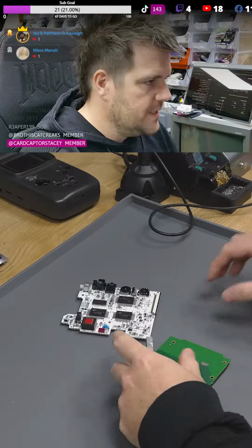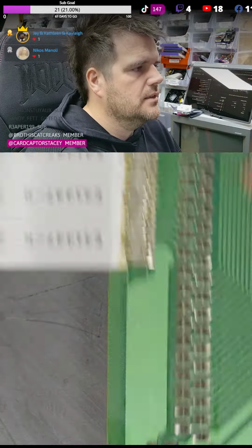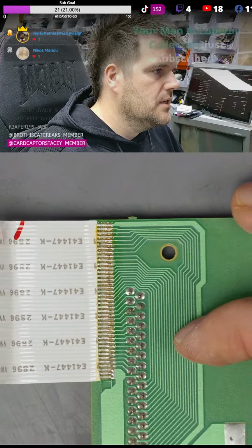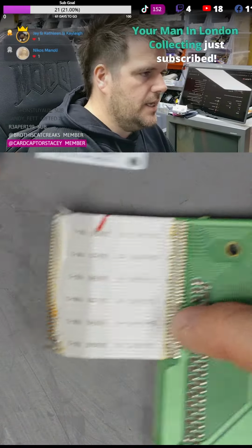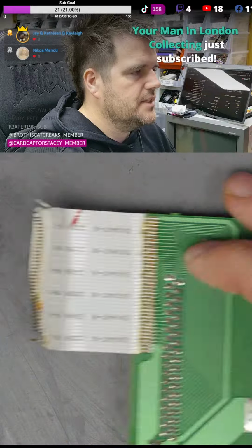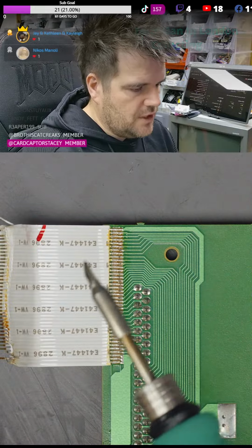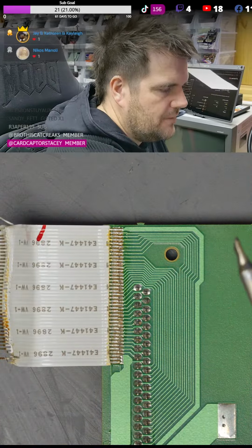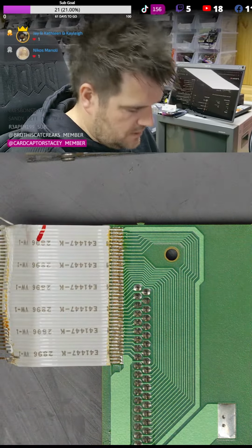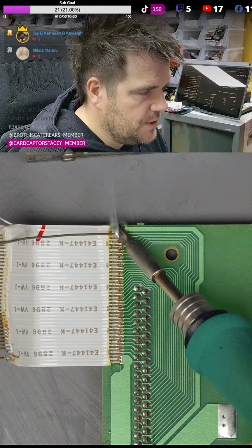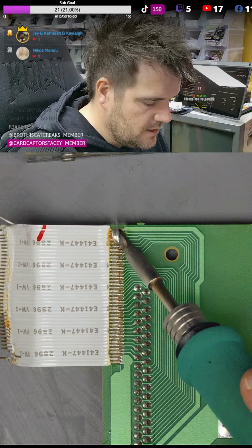So we're going to upgrade this connector, zoom out maybe a bit, to a connector like this. So instead of this ribbon, these ribbons don't really come off well at all. You can't really reuse them. They're very difficult to reuse. So I can get it off with solder or hot air. I did the other one with hot air, so let's just show you the solder instead.